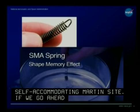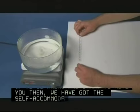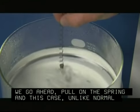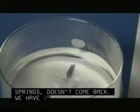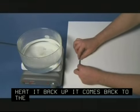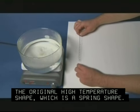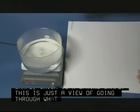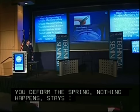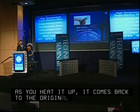We've got the self-accommodated martensite. We go ahead, we pull on the spring. In this case, unlike normal springs, it doesn't come back. We've de-twinned the structure in the material, but as soon as we heat it back up, it comes back to the original high temperature shape, which is the spring shape. So this is just a view of going through what happens here. Again, you deform the spring, nothing happens. It stays in its deformed shape, de-twinned, but as you heat it up, it comes back to the original spring shape, which is your high temperature shape. Can I have the next slide, please?